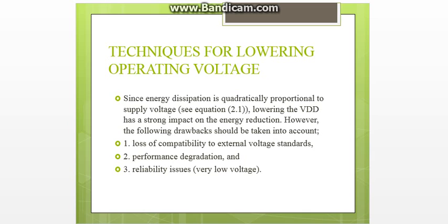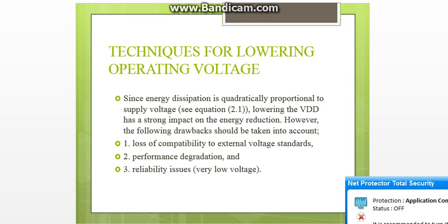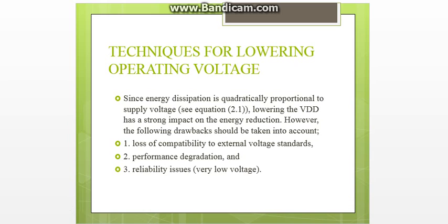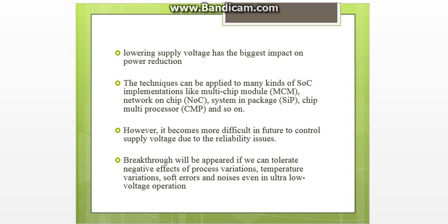Now, the techniques for lowering the operating voltage. Since energy dissipation is quadratically proportional to supply voltage, lowering the VDD has a strong impact on the energy reduction. However, the following drawbacks should be taken into account: loss of compatibility to external voltage standards, performance degradation, and reliability issues.